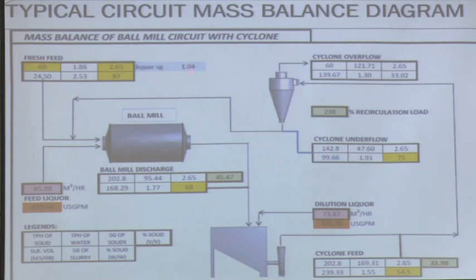For liquor we use 1.03 to 1.05, so you see here. And this is an important parameter. What is the CV? That is the percent solids, volume by volume. I am saying 68%, but that is yielding 45.47. So, I should stay with 68% only, not exceed that. So, that becomes a checkpoint immediately.